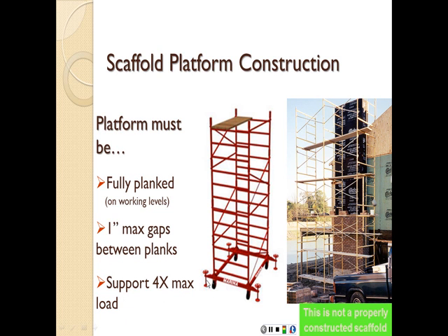We can see here for this one we have the outriggers that increase the base width of the scaffold to improve its strength. We have also the casters, but in this case the casters are going to have some brakes on them to prevent the scaffold from moving while some people are working on top of it. It also has the ladder-like access, so it's already built in, so people can climb that to get to the upper level on that scaffold. It has the cross bracing, which again is going to offer additional strength. So with the exception of the planking, the proper planking, this looks like a good scaffold.